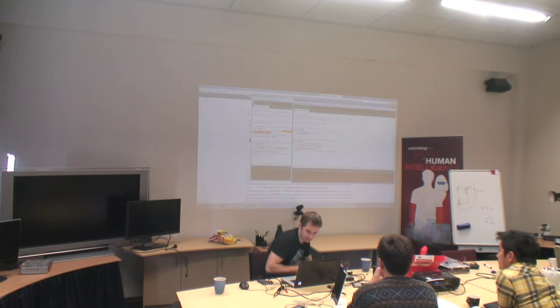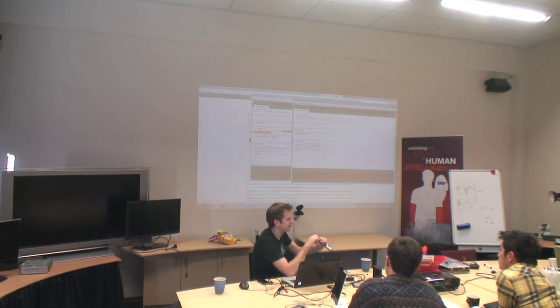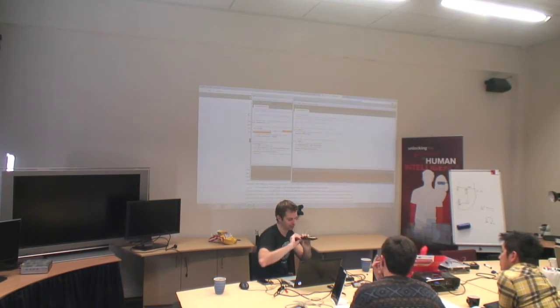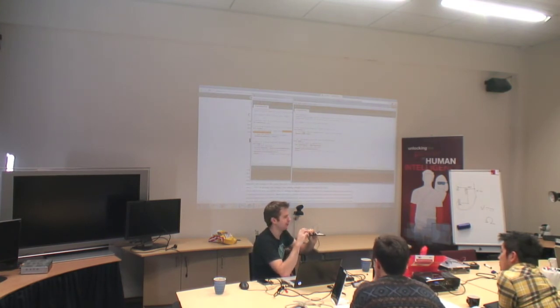Actually this needs to be in an analog port now. So as I said earlier, these are digital pins, they only do 1 and 0. These are analog pins, so they do the other one. If you're doing analog writing, you can actually do pulse width modulation off most of these. The ones which have the squiggly line on it, you see PWM squiggly line, those are ones you can do analog write out of.